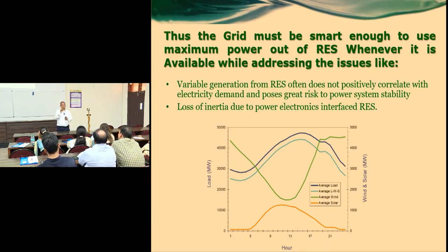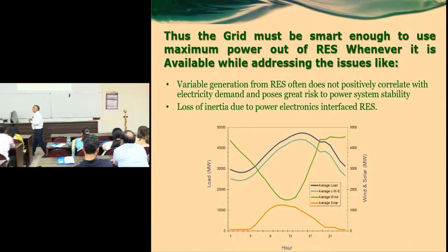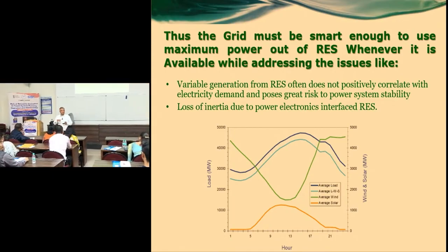So let us say 1 kilowatt generates 5 units in a day. So 20% comes out to 1 unit. So for a 1 kilowatt solar power plant you have to have a 1 kilowatt hour battery backup. If you go to 40%, it is 2 kilowatt hours, and so on. Because 5 units per kilowatt per day is the standard output from a solar plant at a given location in India at least.